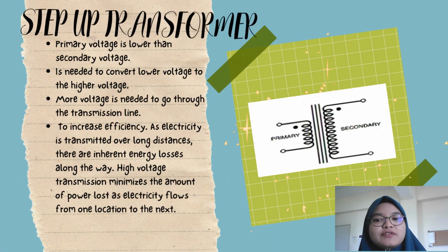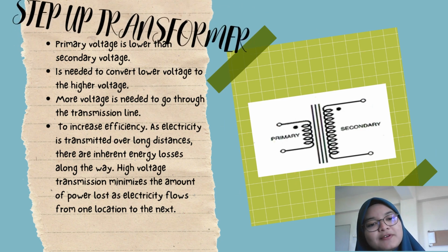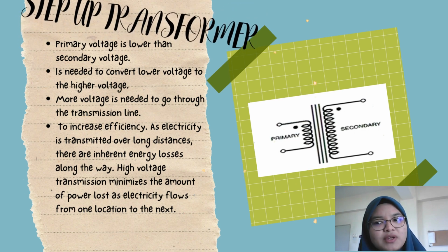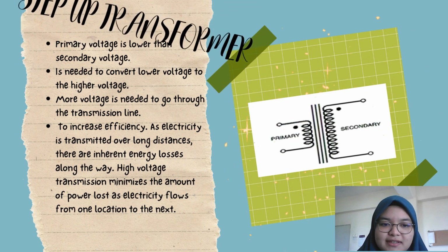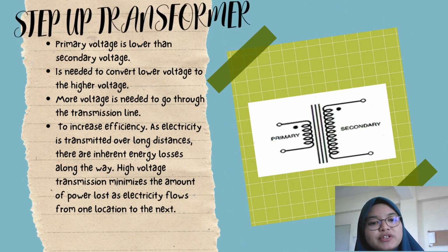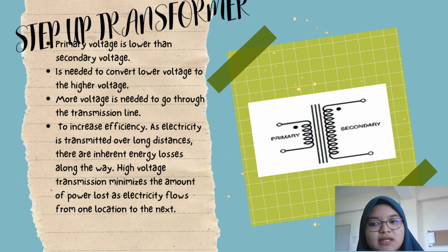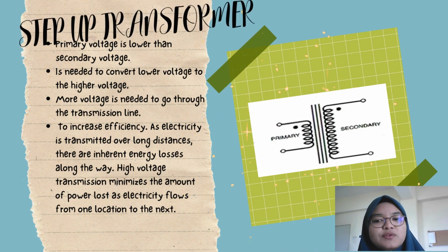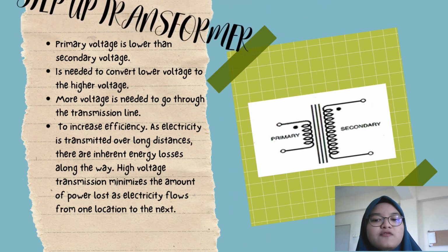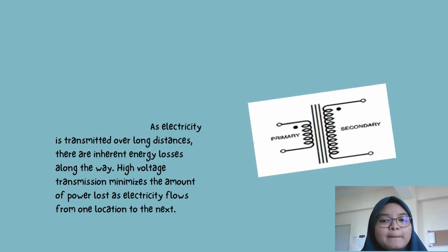A step-up transformer is a transformer in which the primary voltage is lower than the secondary voltage. The step-up transformer is needed to convert lower voltage to higher voltage. Why do we need higher voltage here? Actually, we need more voltage to go through the transmission line. This is important to increase the efficiency as the electricity is transmitted over long distances. There are inherent energy losses along the way. Hence, high voltage transmission minimizes the amount of power lost as electricity flows from one location to the next one.